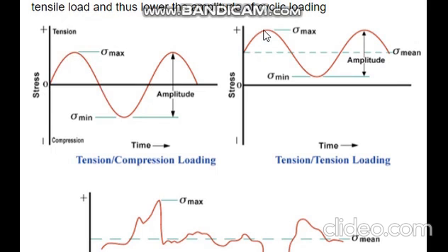In that, again the tension increased, then tension decreased. See, it never went below 0. That means it never went to the compression side. Again, it went up like this. See, it can be fully in the positive, that means on the tension side, it can be fully on the compression side, or it can be like this. So this type of loading is called cyclic loading.